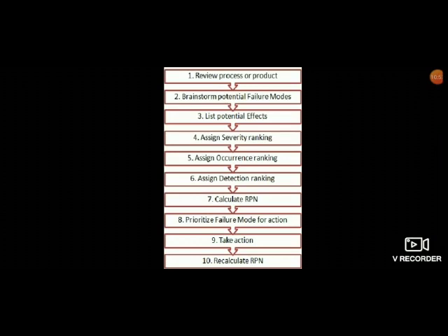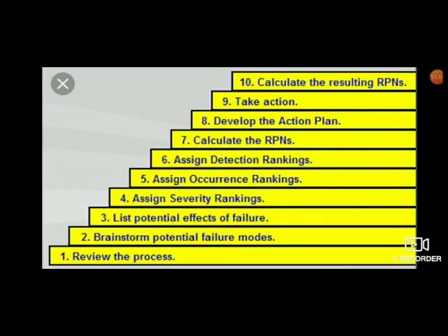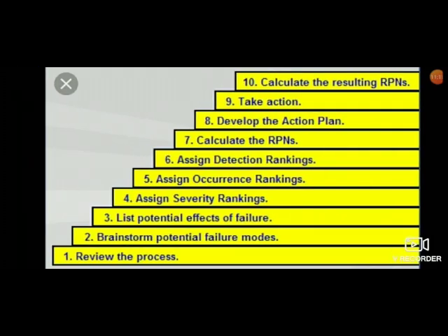Step number 3: list the potential cause or causes for this failure mode. There may be several causes for such failures. Here, consider the operating conditions as potential causes. The next step is to list the controls that are existing in place to detect the cause of failure mode.